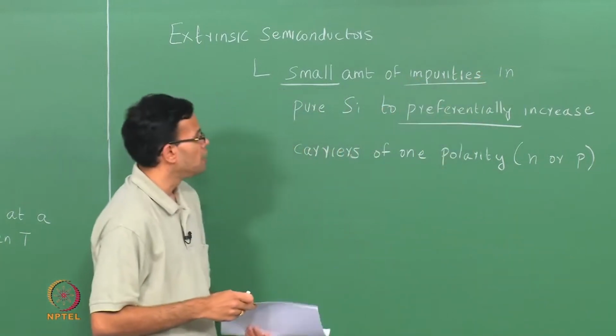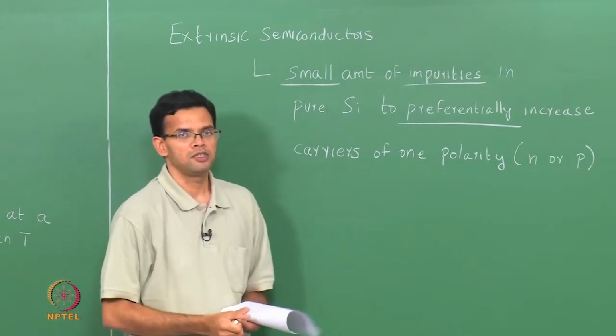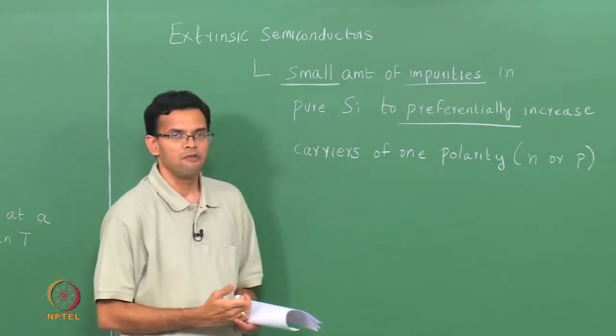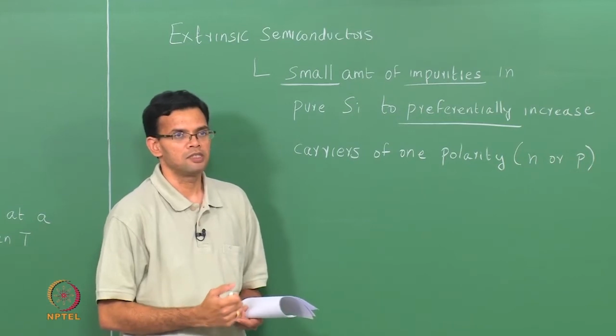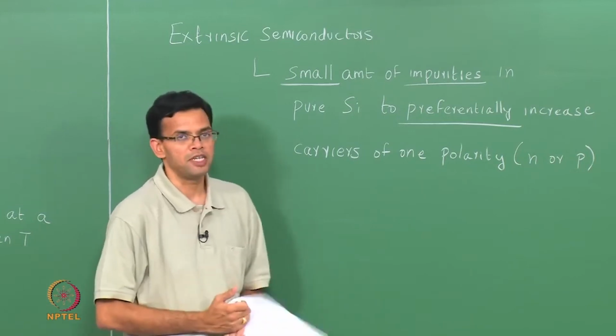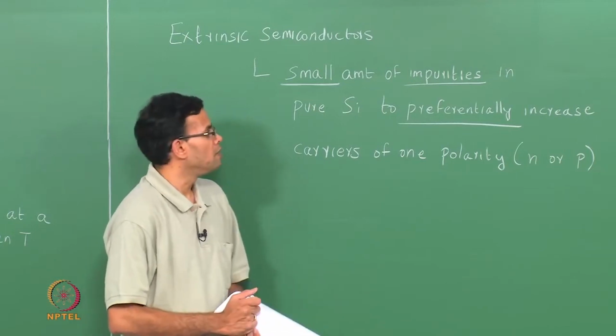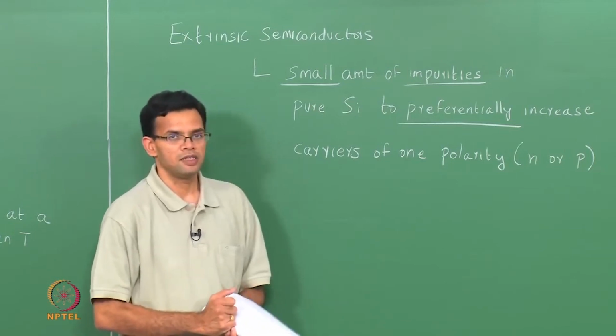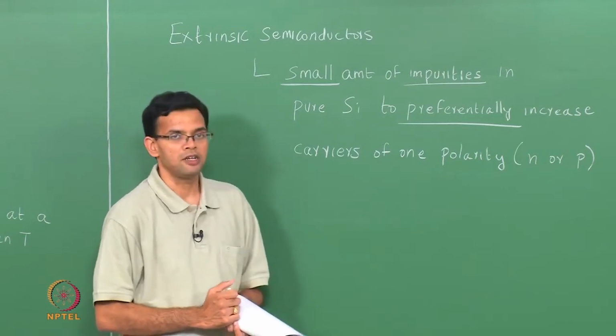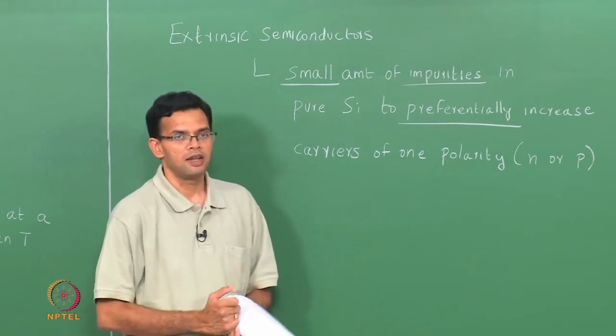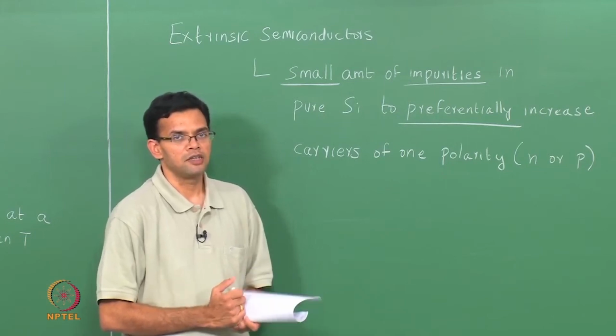When we think of impurities in the context of metallurgy, we usually think of impurities as small amounts of unwanted materials that are there because of some processing problem, but in the case of semiconductors, impurities are carefully controlled materials that are added to your pure semiconductor to change the conductivity.